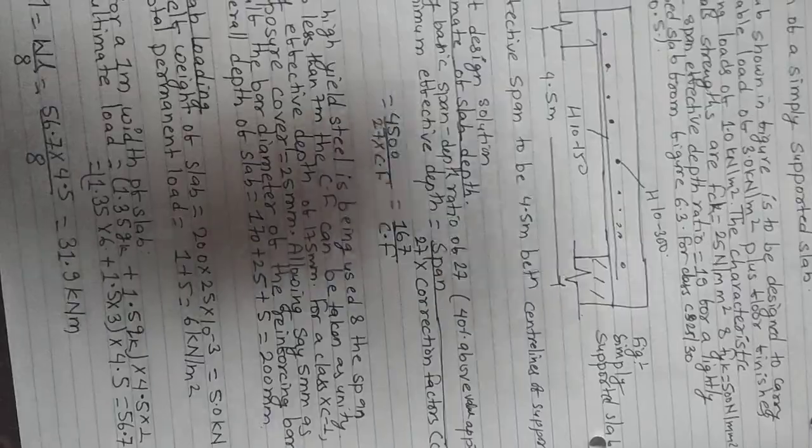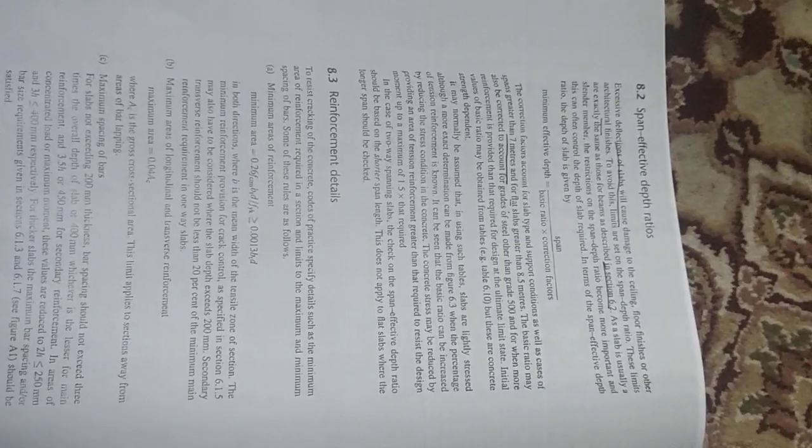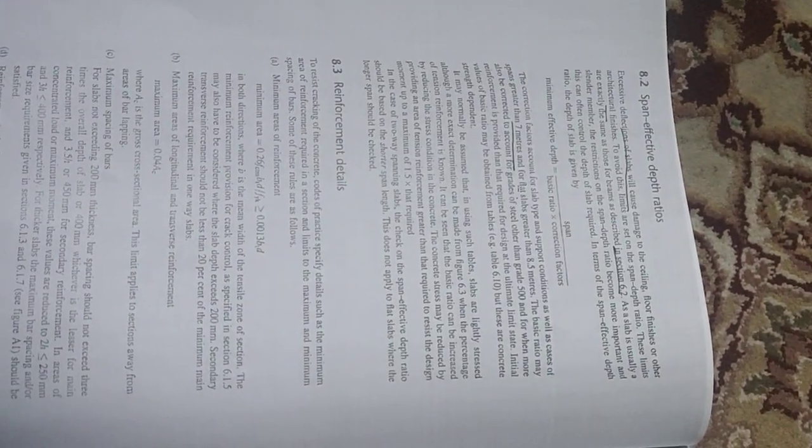For the estimate of slab depth, we need the minimum effective depth, that means span into basic ratio and correction factor. For the basic ratio, this is the figure. This is the figure for basic ratio.